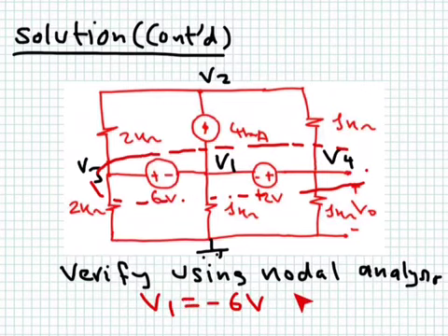I'm leaving it for you as an exercise, and I found it very interesting that you try to build a super node around the voltage source and it still doesn't work, because you have another voltage source connected to that super node. Then you have to make the super node even bigger. So please try to sum all 6 currents flowing out and set their sum equal to 0 to obtain one equation between V1 and V2. The second equation can be obtained by writing KCL at this node.